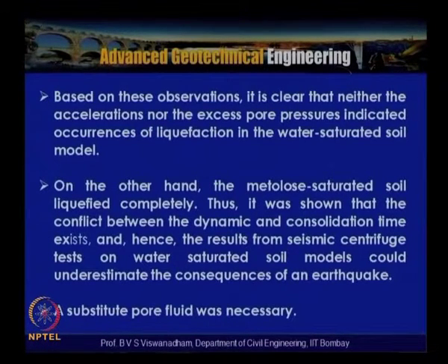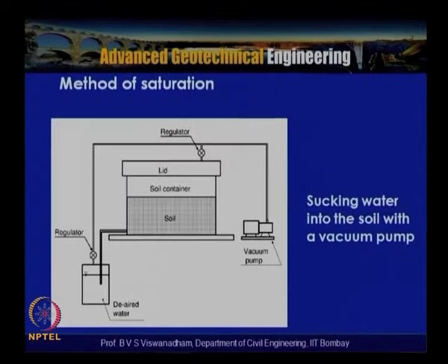That is what we have been discussing: if you use water as the pore fluid in seismic centrifuge model tests, the results can lead to underestimation of the consequence of an earthquake. So this implies that a substitute pore fluid is necessary for carrying out seismic centrifuge model tests.